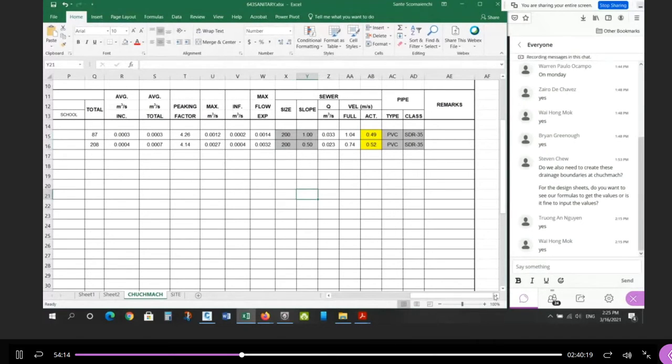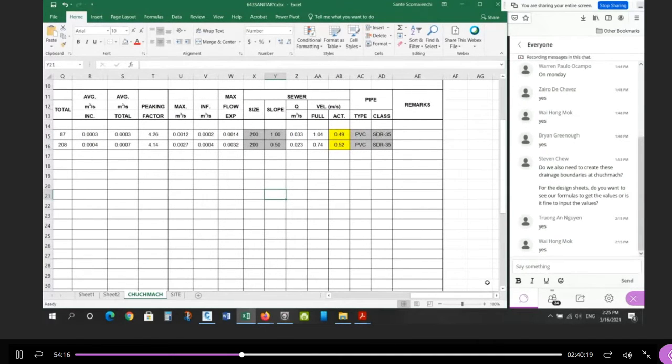Now, what are we looking at? And this is the one thing that they don't show on the spreadsheet, but I like to calculate it. I'm going to look at the percent full. So I'm going to look at equals the actual flow, that's the expected flow, divided by the pipe capacity. Right? How much flow is actually coming and how much can the pipe actually take? And this will be a percent full. Right? And if you convert this to percent full, you'll see it's only 4% full. So that pipe has a lot of room. There's a lot of room.